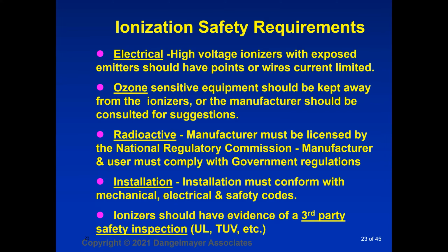Ozone is a byproduct of corona ionizers. It's a small quantity. You should, in general, think about keeping ozone-sensitive equipment away from the ionizers, or get an evaluation unit and see if it produces ozone in an amount that's hazardous to something else that's ozone-sensitive in your environment.